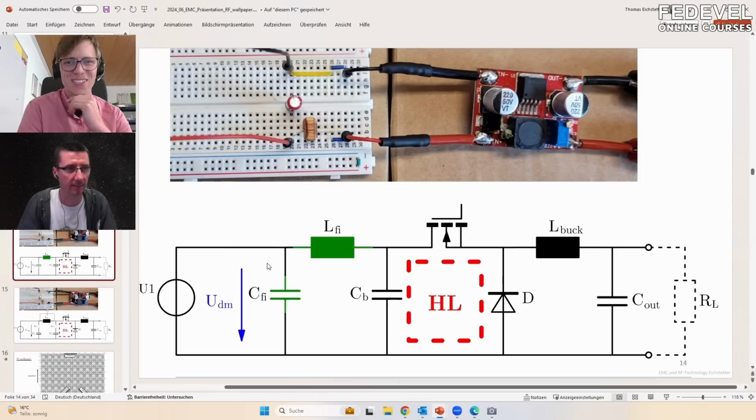Because the impedance, which is seen here, is first very high, the noisy voltage will stay here. And in addition, you have this division ratio, which we will later on see in the picture very well, and this will very easily divide your voltage.